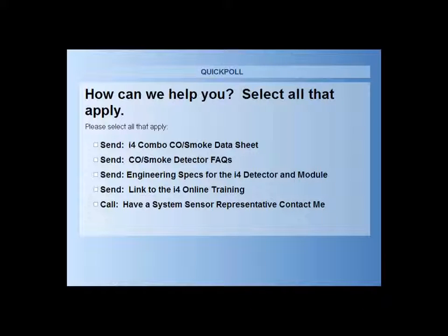Good. Okay, a question about battery backup. Does your control panel have a battery backup? It is a requirement for the control panel to have a battery backup. I don't know the exact specifics, but there are some requirements around, I believe, 24-hour battery backup. Okay, good. Let's see. They're writing here, I believe the local code for smoke detector placement is within 18 inches of peak of ceiling. They believe we stated 3 feet for CO, so how do we address the combo?